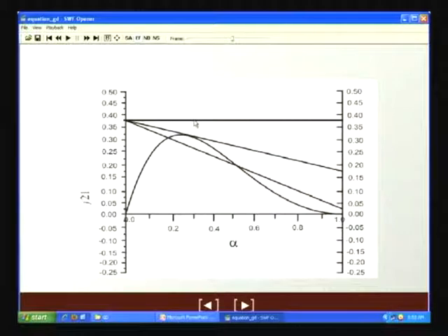So, beyond that, if we increase either of the flow rates, we find that there is no point of intersection between the straight line and the curve. And it is quite expected that beyond the flooding point, there is no stable operation. Either there will be a change in the flow pattern, due to which this curve is going to change, or there will be some amount of rejection of material from the flow passage. Whatever it is, the flow is not going to be stable, and it is not going to retain the same interfacial characteristics as it had earlier.